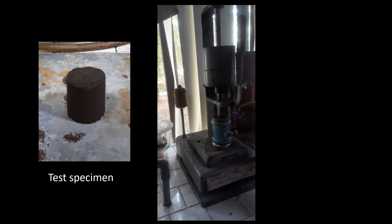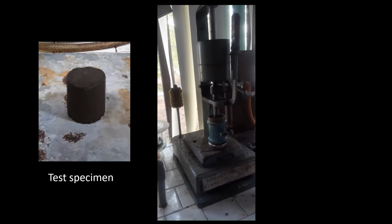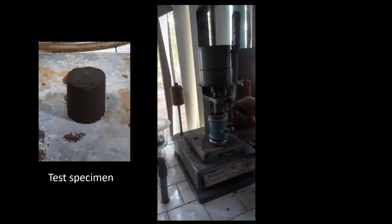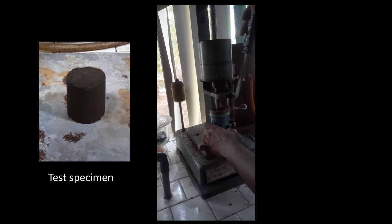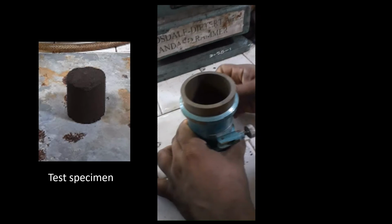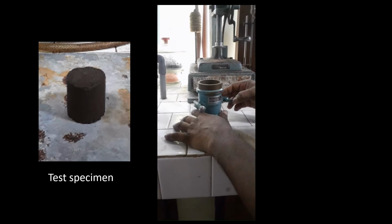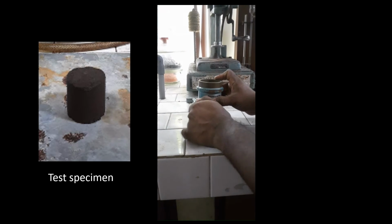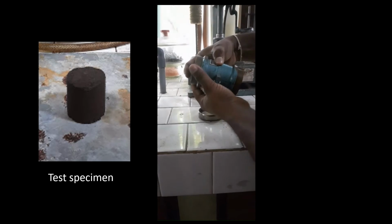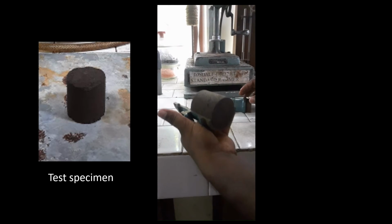After ramming 3 times, the top of the plunger shaft should be level with the center line of the tolerance plate to get the 2 inch height specimen. We have to repeat this procedure by increasing or decreasing the weight of sand until we get the exact height for the specimen. This is the standard specimen.